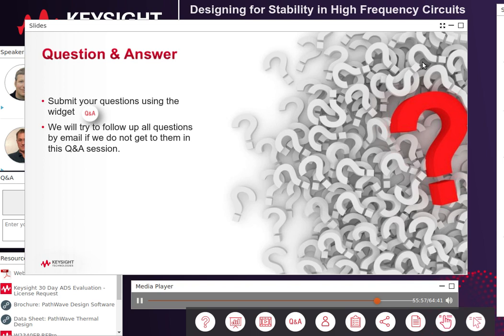It needs an associated parameter, similar to how the Rollett stability factor has an associated stability measure as an associated parameter. And we're calling this associated parameter for the loop gain the port impedance or the open loop function. You can find that in the help pages in ADS under WSP_ZOP. That's ZOP, the open port function call that can be accessed.